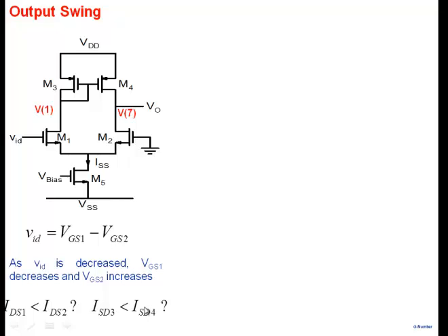So what happens now? What happens in this differential pair now? Of course, the currents in these two are not going to be identical, because as you shift current onto this side, the current here reduces and this voltage falls. But even though they are in saturation region, the voltage here is different from the voltage here in general. So current here can be a little bit larger than this, but not too much. Why? Because both of them are in saturation region. When both are in saturation region, the current here can be larger than the current here, but the difference will only come about because of channel length modulation. And that is not too large a quantity here.